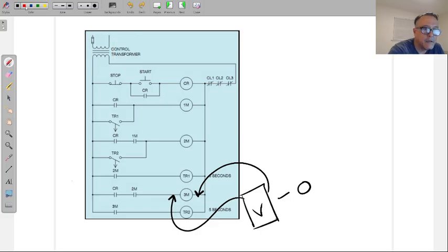And now once I establish that there is power, if there's no power coming into the circuit, great, I got the problem solved. I mean, not solved, but I got what the problem is, and now I can go around fixing things. Maybe that little fuse is blown, whatever. But if I do have power going in, now point to point. What is the first place where that power lands? Well, the first place it lands is here. Do I have power there? Yes, no? Okay, on to the next thing. Power there, yes or no? Yes, all right. And we go on through until we find the point